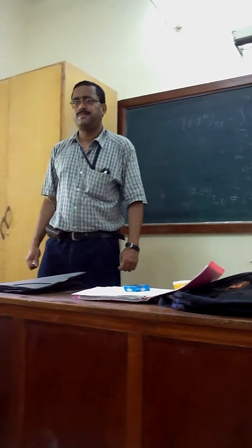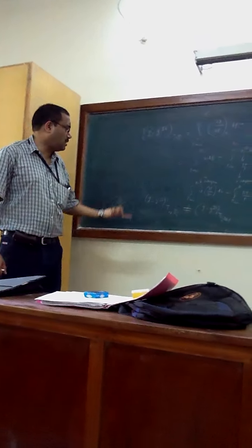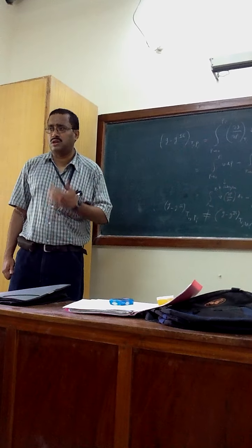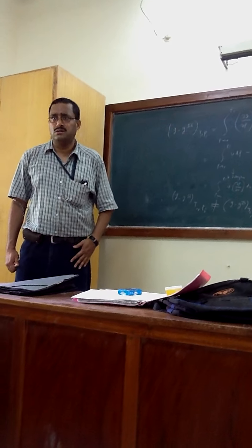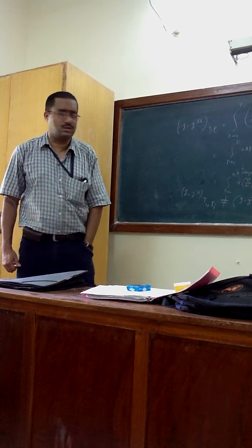It cannot be. So get the formula. So I ask that you find the Gibbs energy departure based on the Peng-Robinson equation of state. Okay, so that is the structure of the question.